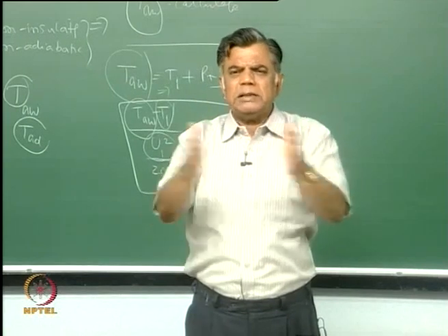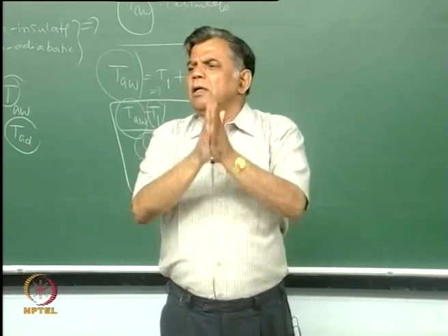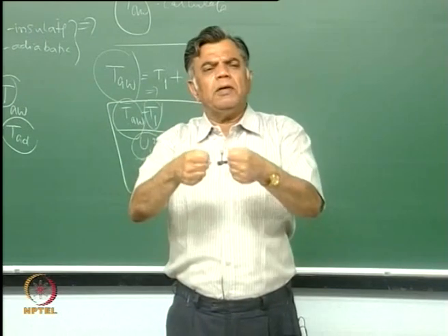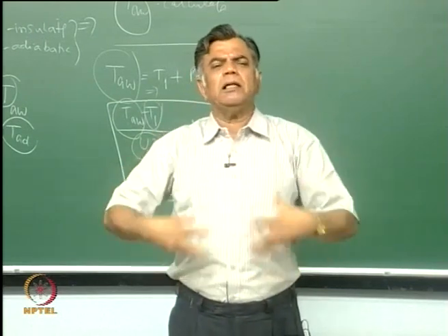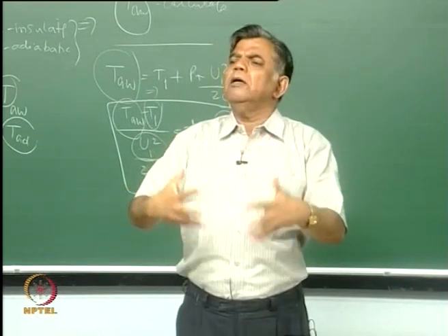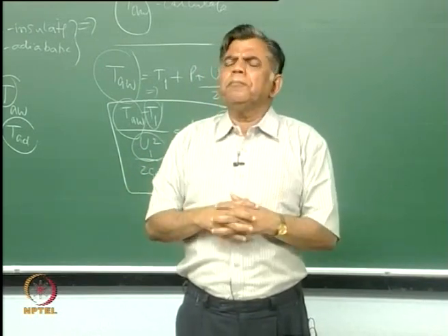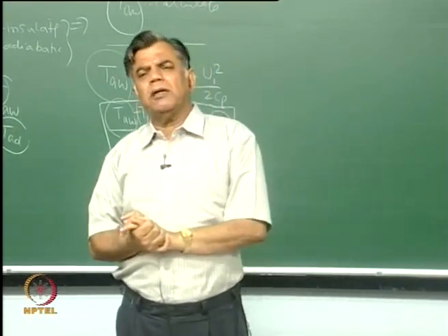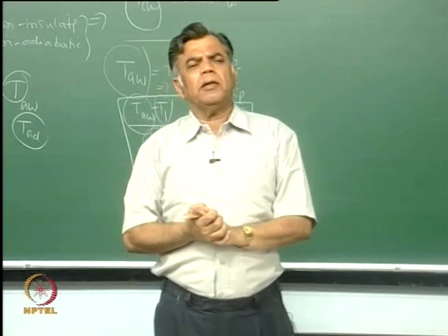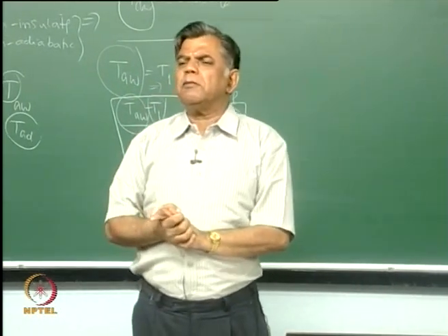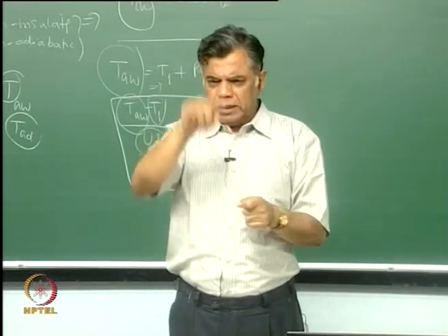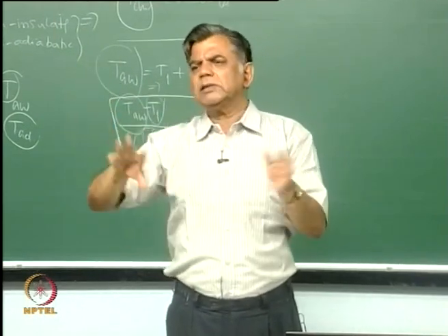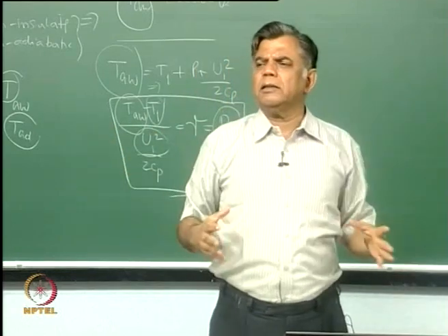Once you put that in, that is the right equation for heat transfer, and that is a function of the Prandtl number, which comes through a recovery factor. Recovery simply means the frictional heat that is being generated is being recovered as much as possible within the system. That is all it means. So to solve this problem for heat transfer in all convection systems, get the adiabatic wall temperature through the recovery factor, which is simply a function of the Prandtl number. We can actually plot all this as a function of Prandtl and Eckert numbers for various flows, and go back and calculate the rate of heat transfer.